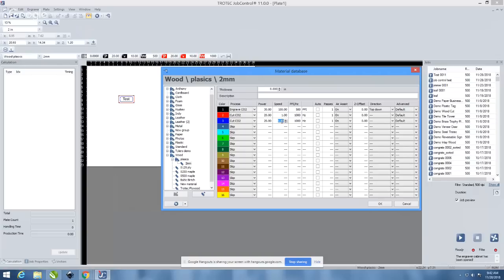For cutting through thicker materials, like maybe a 1/4 inch piece of wood, you'll often be less than 1. On our 100 watt machine here, we might be at 0.7 or 0.8% speed to get through a 1/4 inch piece of acrylic. So it depends on the thickness, but for it to be fractional is completely normal as far as that percentage is concerned for cut speeds. Yeah, and you can go 0.75, 0.76, so you can adjust the percentage to that degree, and that usually helps with different cutting materials.